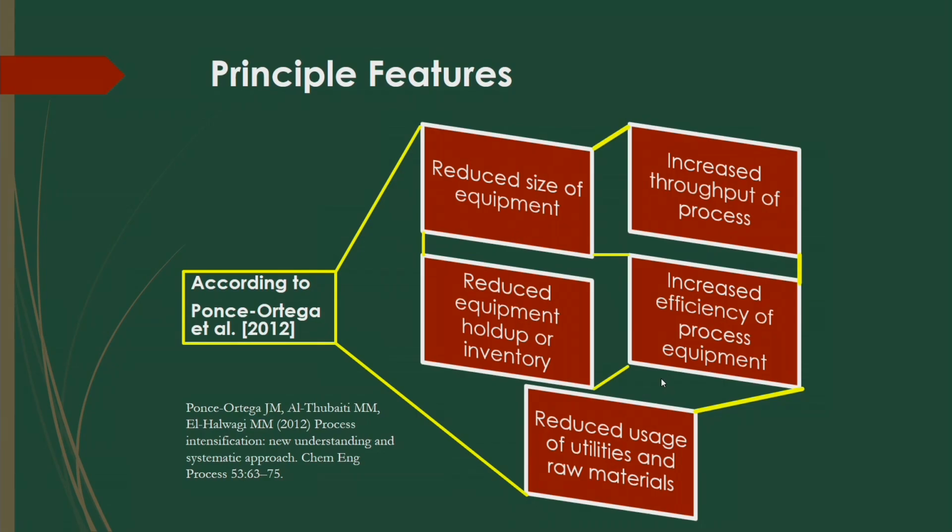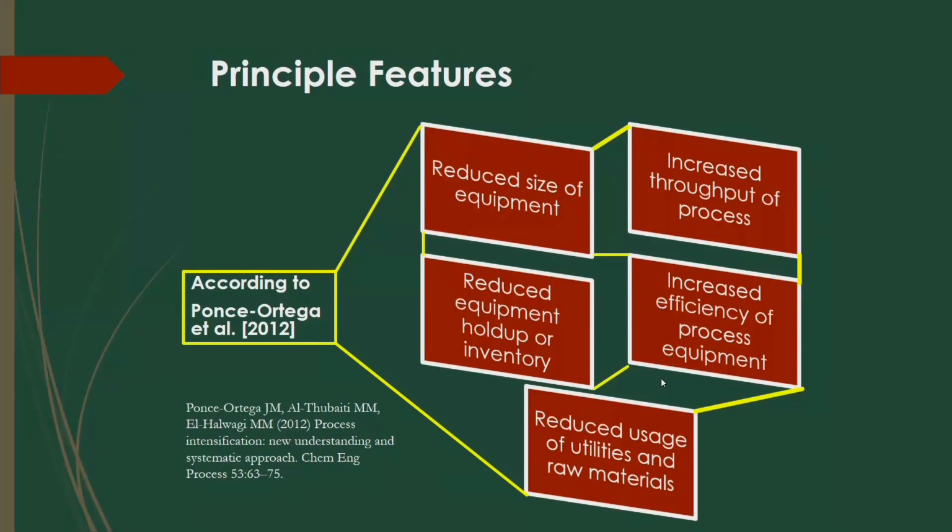And also process intensification can be done by increasing the throughput of the processes. Sometimes in turbulent motion or turbulent flow you will see an intensification of the process, because at high throughput you can get more interaction of the molecules of the process, as well as more mixing inside the bed. So, high throughput is also one important factor to increase the intensity of the mixing of the process, based on which you can get more output.